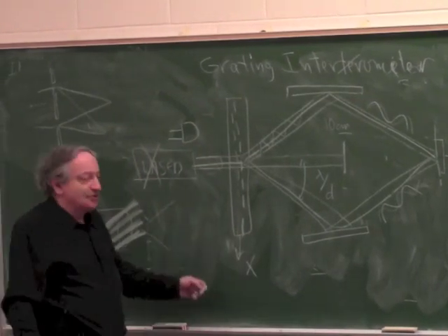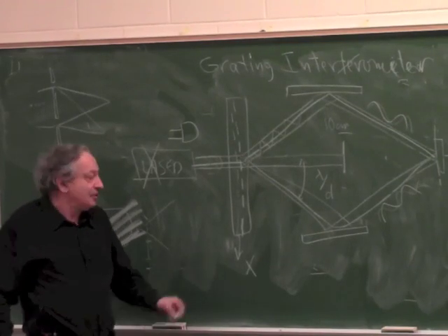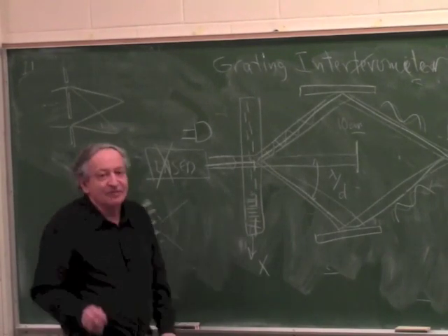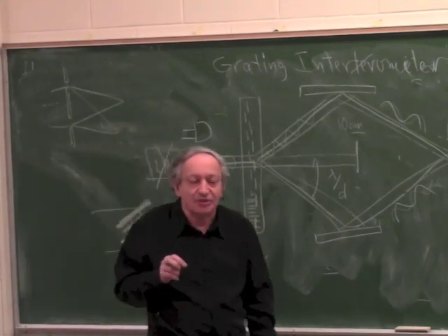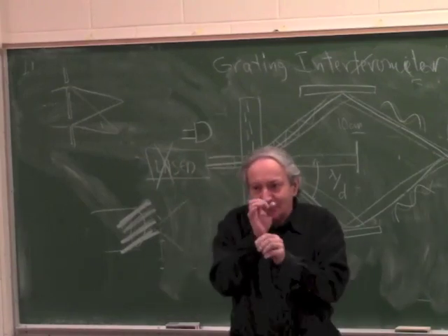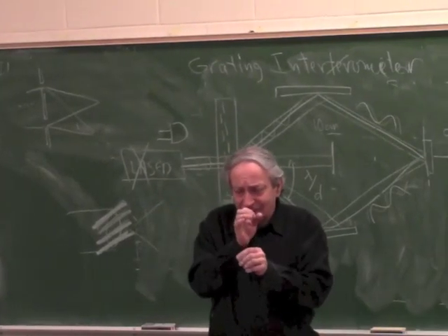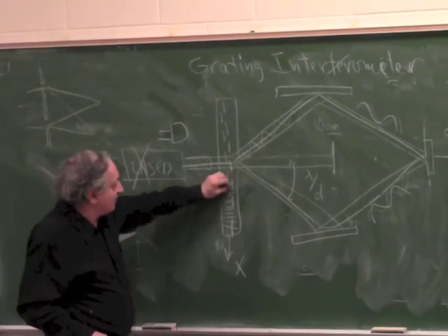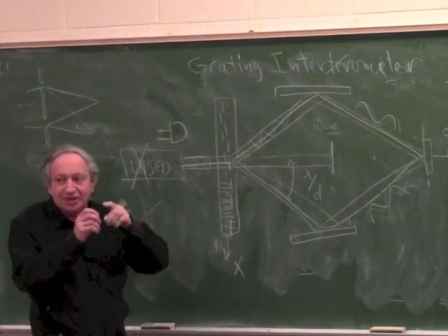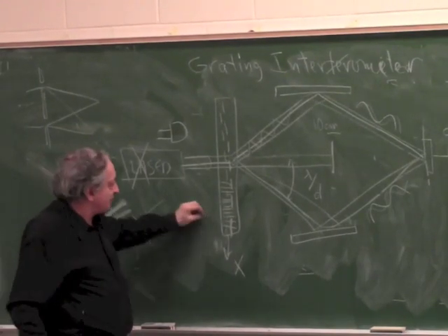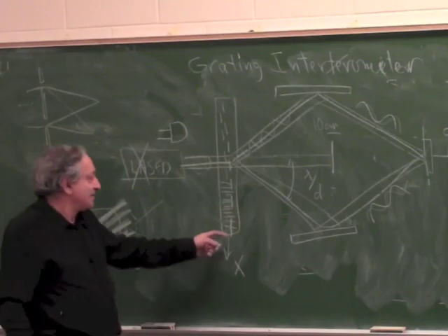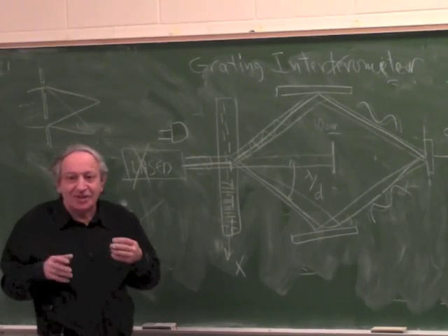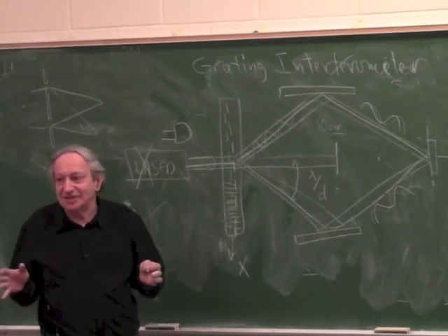So this is a very good position sensor, because you can take this grating and make it very, very fine. And typically when you make a very fine grating with a traditional encoder, you have problems because you have to resolve the lines. Basically what I'm comparing this to is a linear encoder with the same fine grating where I want to read the line position directly. But if I want to read the line position directly with a microscope, the finer the lines, the harder to read. I have focus problems. Here I don't need to focus anything.